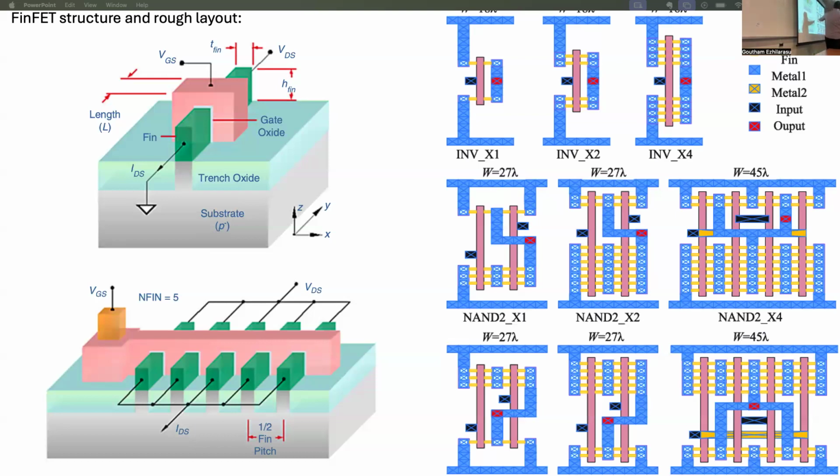And why, you may ask, sometimes use a smaller inverter? It really depends on your circuit. Sometimes you care more about the area, or there's also optimization. Sometimes using a 1-width transistor is more optimal, because you have to optimize area, power, as well as speed. When you do that optimization, you have certain sizing for all the gates. So that's why you have all these options.